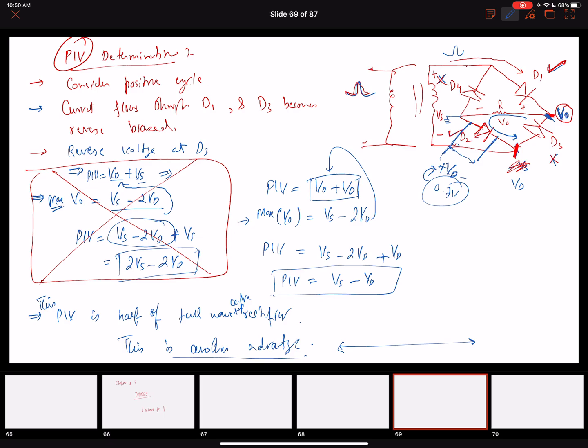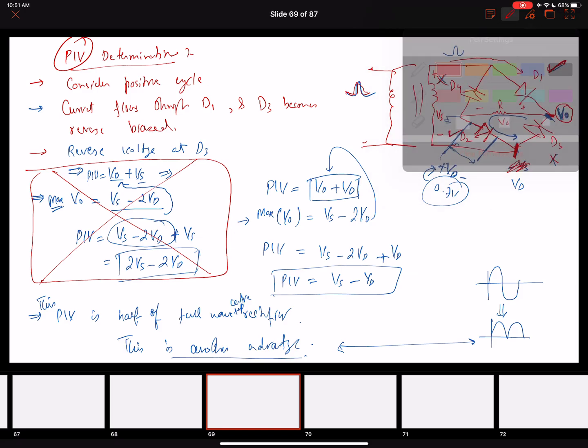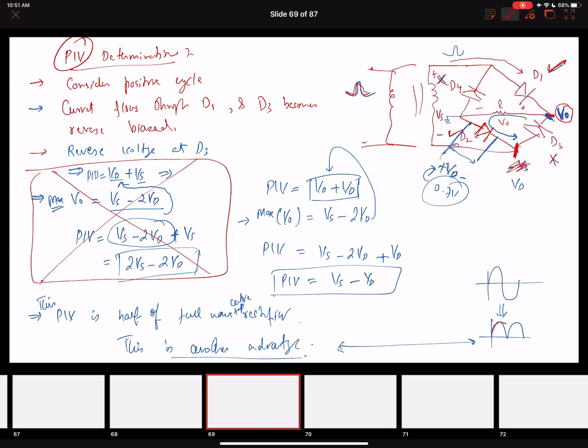So this is how you can find the peak inverse voltage of a rectifier circuit. We want to do one more thing in today's lecture: how we can further reduce this variation. We ended up converting this to this, and our goal is to get a very small ripple voltage, a better DC. For that we need to develop another circuit called a peak rectifier.